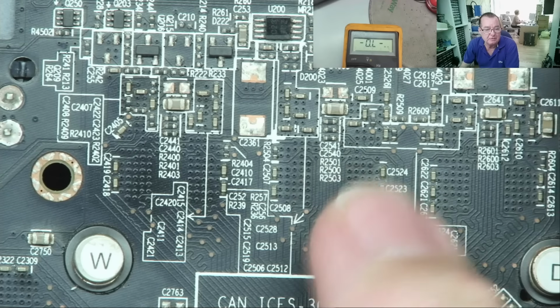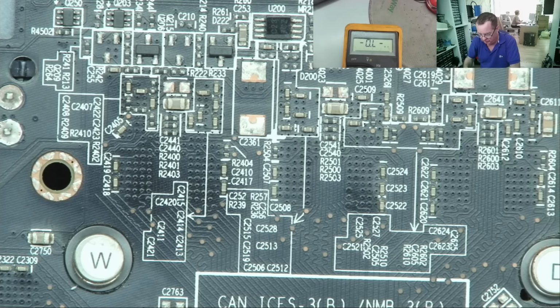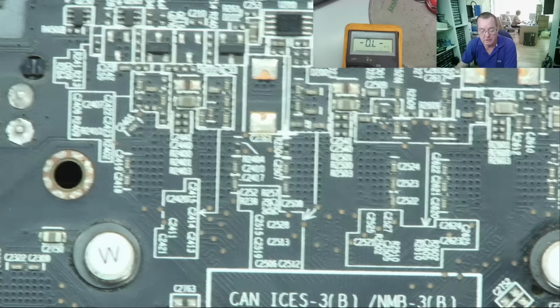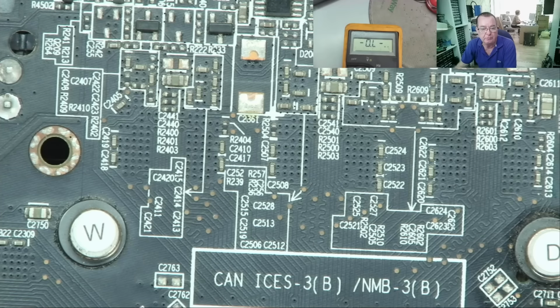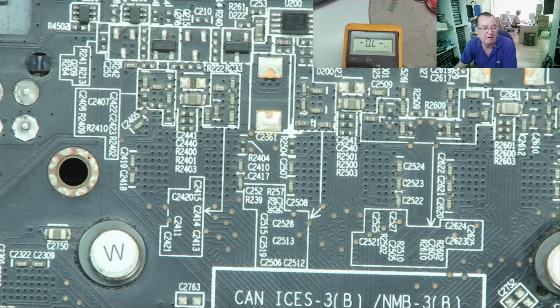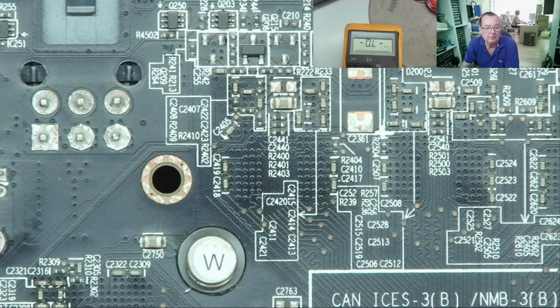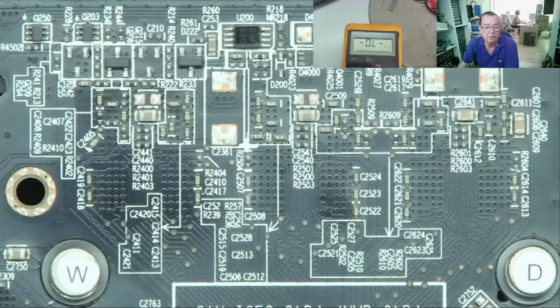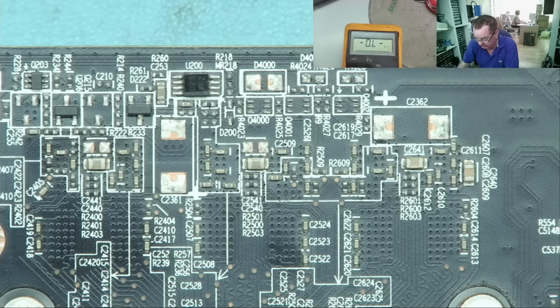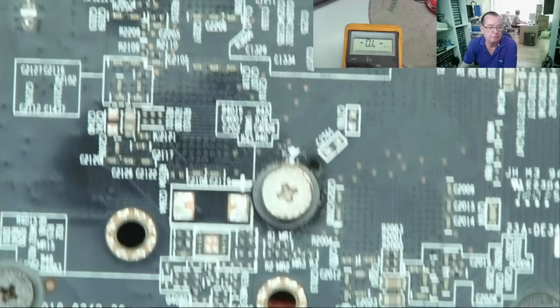This is a bit darkened here. This is probably underneath the RAM chips. Do we see that on the other one? No, we don't. So it's possible that on the other one, the RAM chips have been overheating, maybe telling us we actually have a RAM problem on this one. Can you see that? Yeah, there, okay. So that's one thing I would bear in mind with this card. Yeah, we have the same here, and again, I suspect this is behind one of the RAM chips.